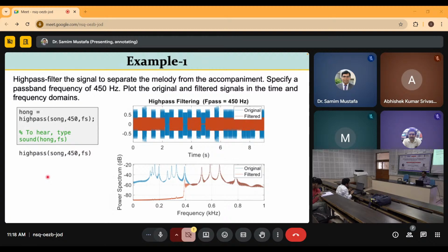So if you are using the high pass filtering, then you apply the high pass and then deduct it from the total response. That will give you the low pass data. Means frequency content below the fundamental frequency of the bridge will be preserved and the rest will be eliminated. Okay, because it is produced by the dynamic component of the bridge.